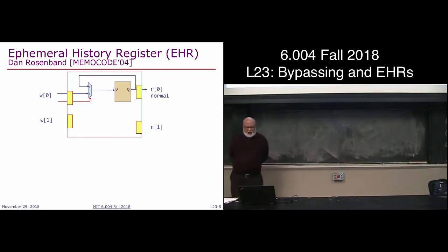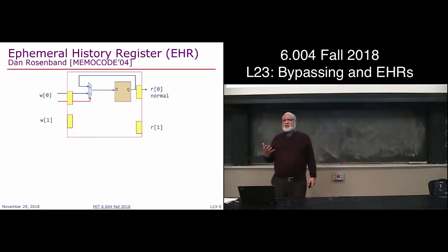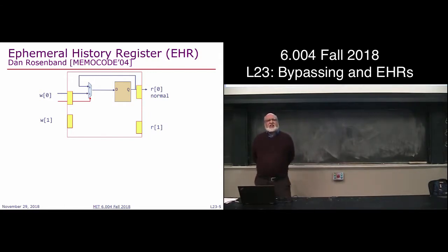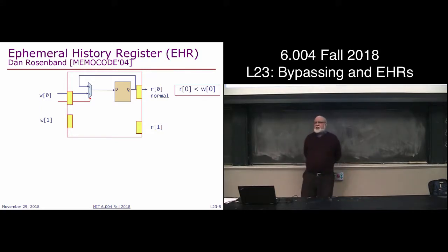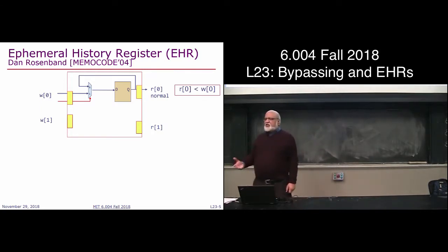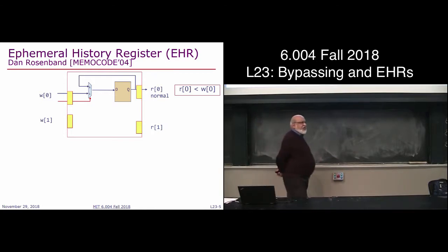of that work. But just imagine I'm designing a module, and what is my register with enable? That's what I have shown you on this slide, right? You have a flip-flop, and you keep feeding it back. So if there is a new write coming in, it's enabled, then the new value gets captured, otherwise it doesn't change its value. So that's what reads and writes behave like in an ordinary register. This is the normal behavior, and if you do them in parallel, it behaves as if read happened and only after that write happened, because the effect of write can only be seen in the next cycle. So far so good?